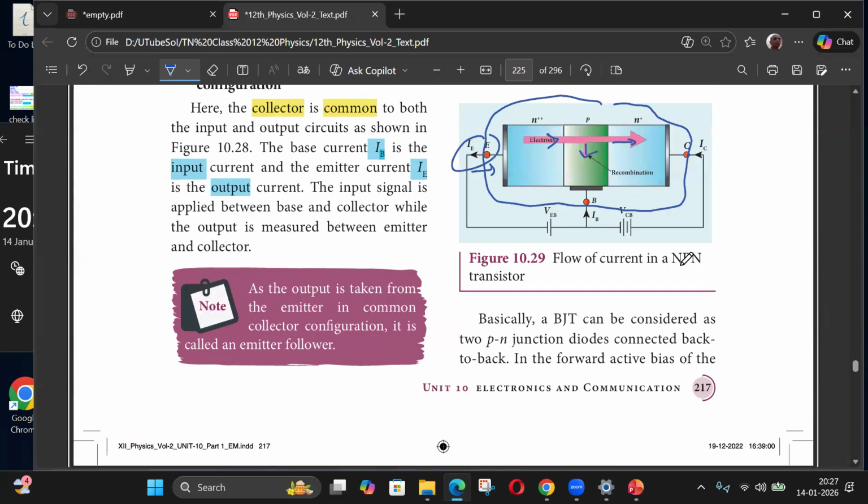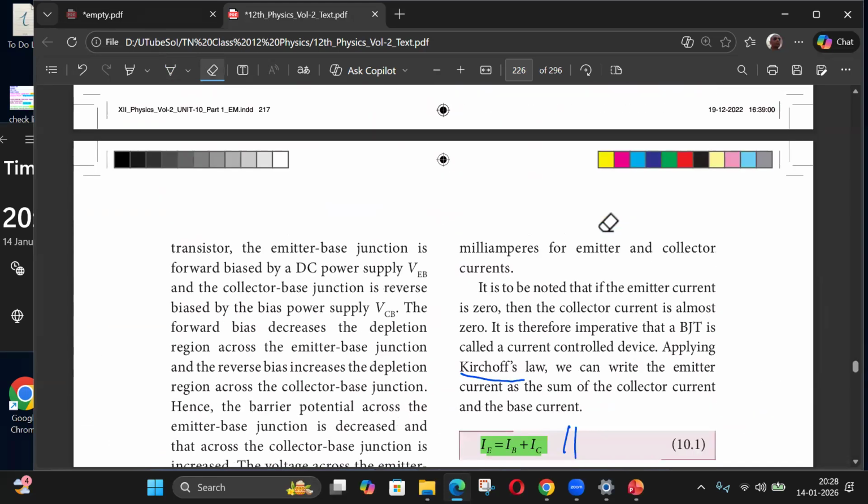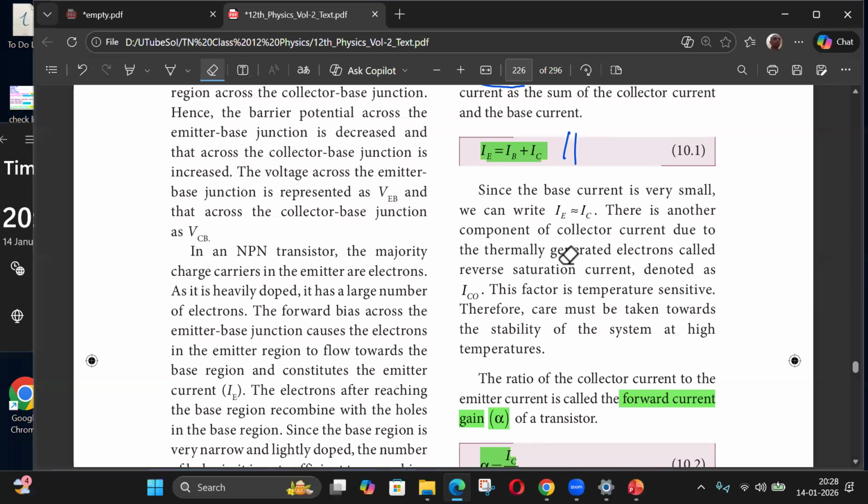Another thing is that by design, the base current will usually be small. That's why it is shown figuratively here by a small arrow, while the thick arrow is a little bit more. So if the emitter current is 1, the collector will be 0.9 amps and the base will be 0.1 amp. That's why they say IE and IC are approximately the same.